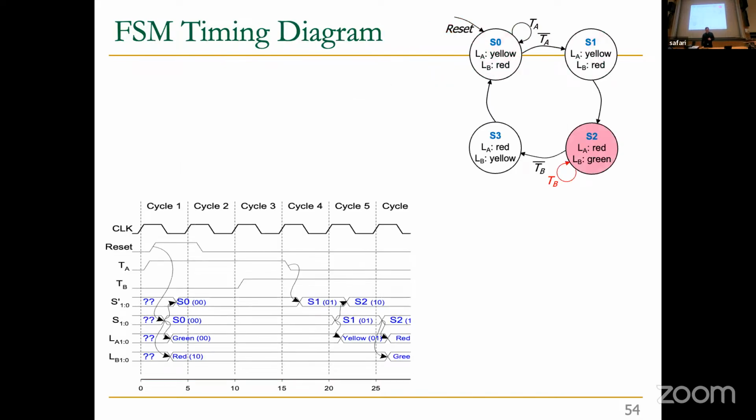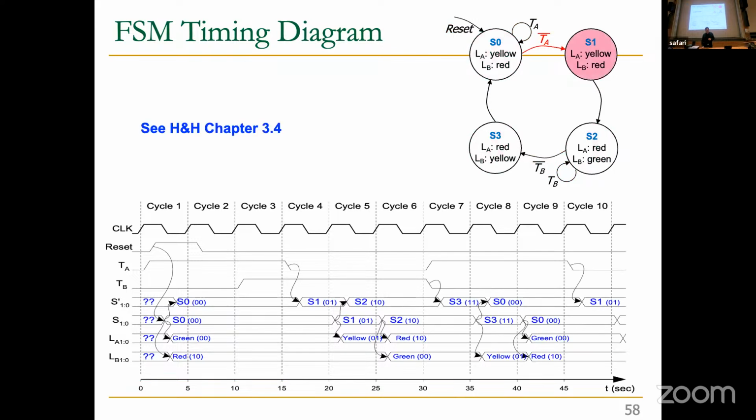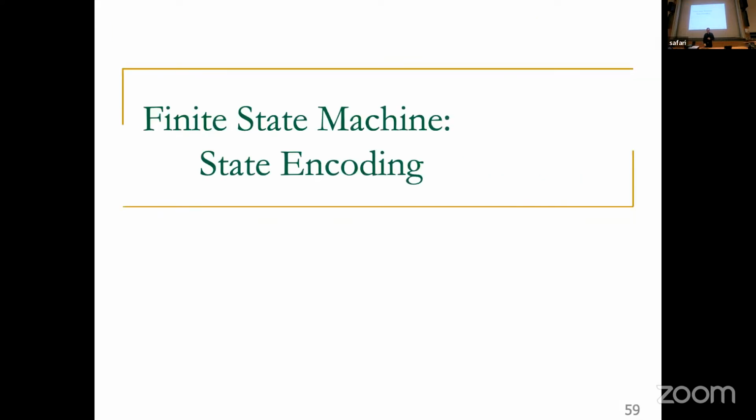Okay, so let's go over. We're going to see more of this. And we're going to see in timing and verification that it's really a sequential system that we're talking about. A sequential system, beginning of the clock cycle, ending of the clock cycle, there's some combinational logic, and you have to accommodate the longest combinational logic delay. If you cannot accommodate it, divide the work into multiple clock cycles.